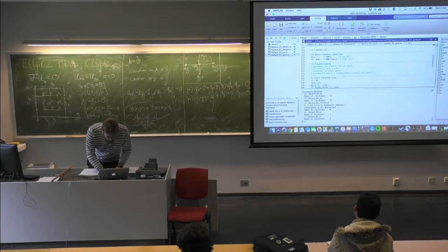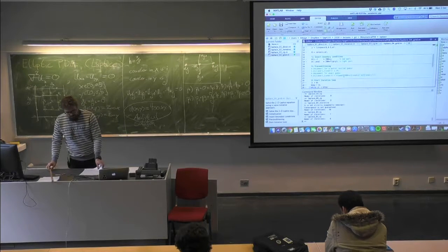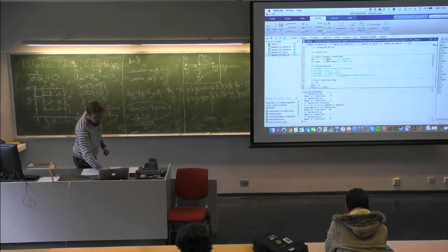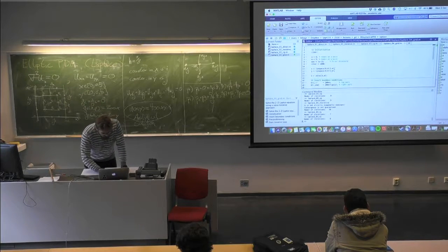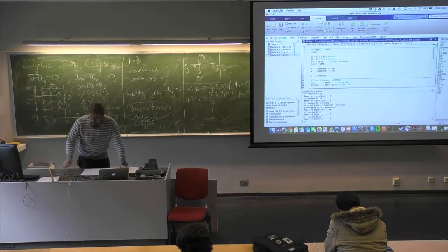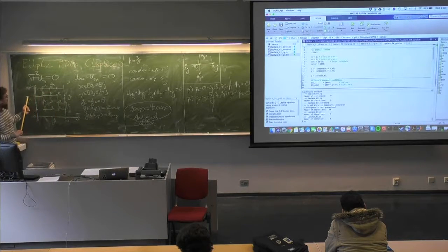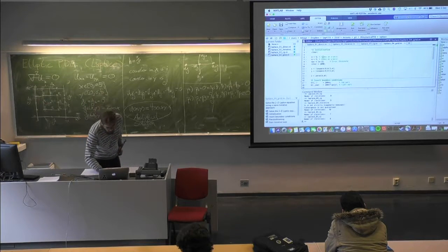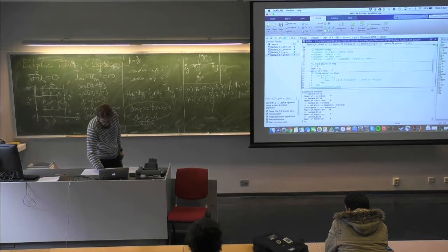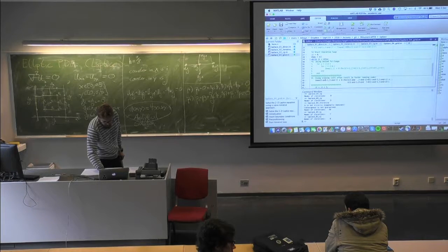A fourth way of solving it is to actually just run through all of the equations. Again, it is easier to set up, just doing it on a grid by grid basis. So here you see the nodes. I've just picked all of the nodes, so yeah, 5 by 5 instead of 3 by 3 because I have to calculate. Here's the boundary conditions, so the top part and the right part. And I start an iterative.